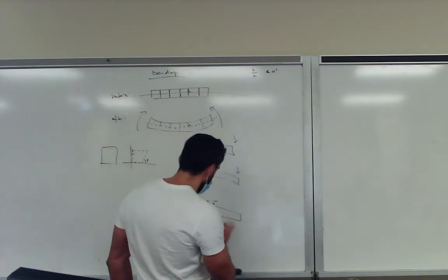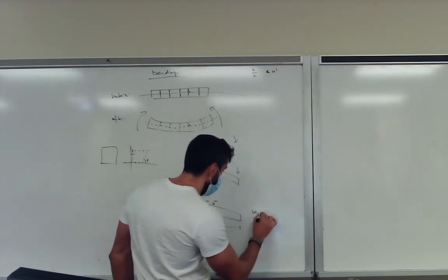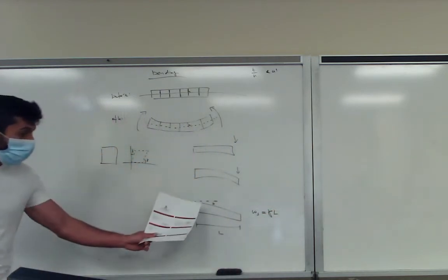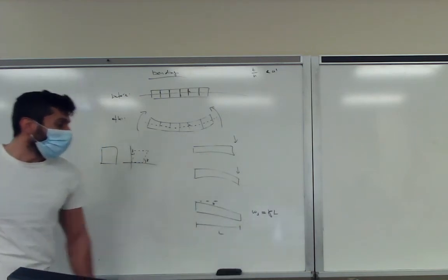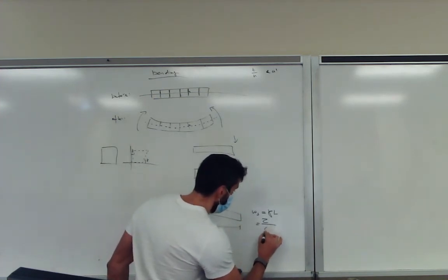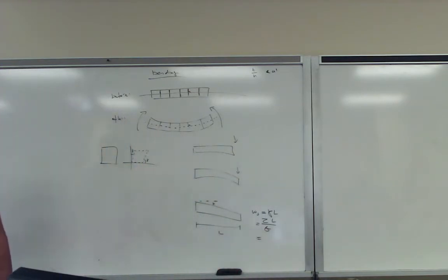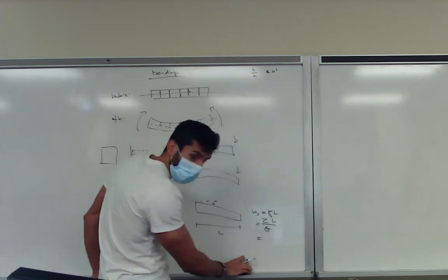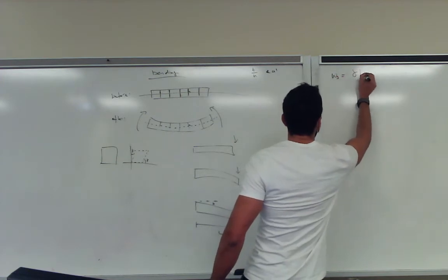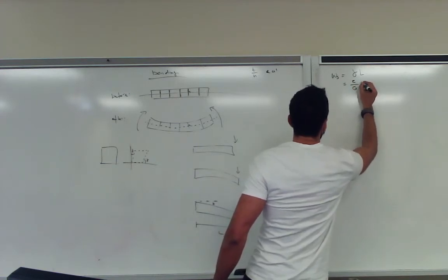So we can say this is length L. The deflection in W due to shear, W_s, is equal to the shear angle, which is equal to the shear strain, multiplied by our length. We know shear strain is equal to shear stress over G. So W_s is equal to shear stress over shear modulus multiplied by L.